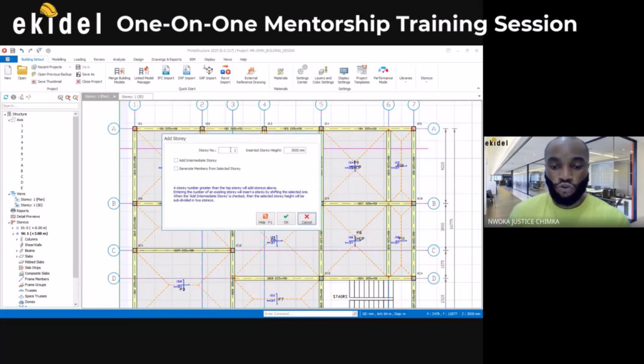Now they ask me for the number of stories. Currently we have story 1 alone. Since this is a 1-story building, I'll come here and say 2, that is the ground floor and the first floor. Now, if I want to generate story, that's to copy the columns and the grid to the next floor, you must make sure you check here, generate story. Else, if you don't check this, it is only your grid lines that will copy.